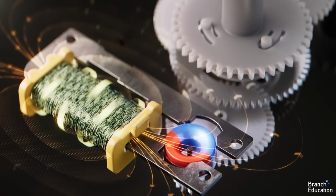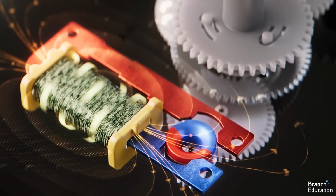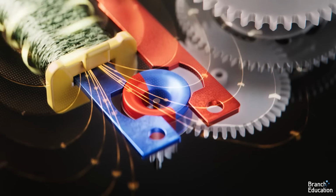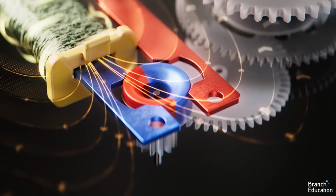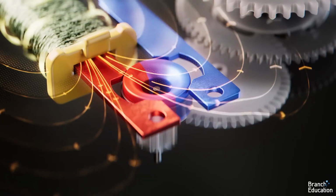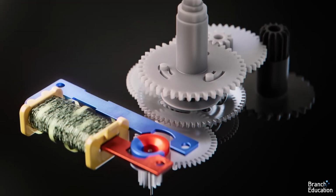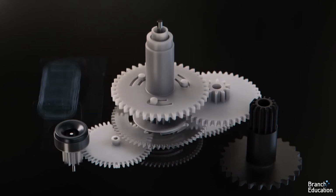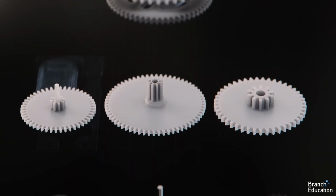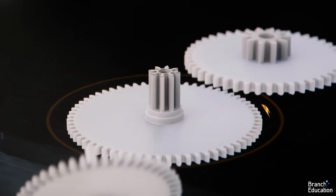Every second, the electromagnet switches directions, thus causing the magnet inside the driver gear to rotate 180 degrees in order to align its permanent magnet with the fields produced by the electromagnet. Therefore, the driver gear rotates fully around once every 2 seconds. Most of the gears in the gear train are composed of compound gears, each of which has 2 different gears, one on top of the other.